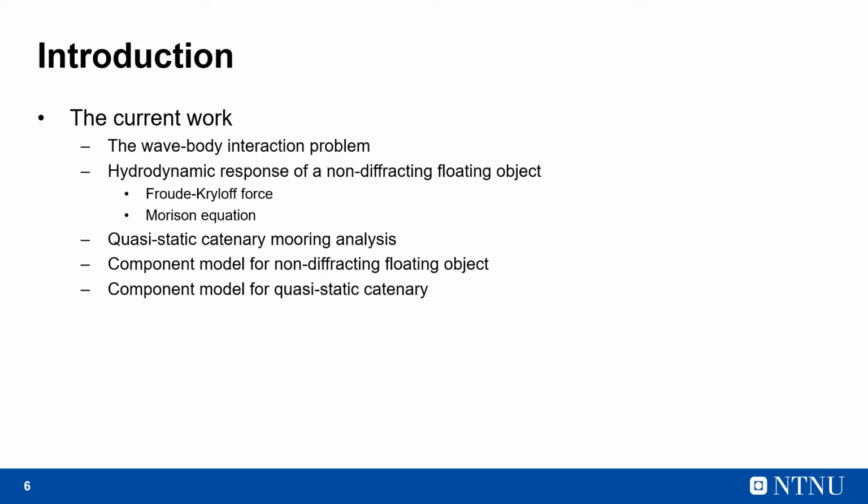In the current work, we will look at the wave-body interaction problem. We will then look at the simplifications in case of a non-diffracting floating object. We will talk about a catenary mooring analysis within quasi-static catenary theory. And we will look at how the models for the non-diffracting floating object as well as the quasi-static catenary mooring